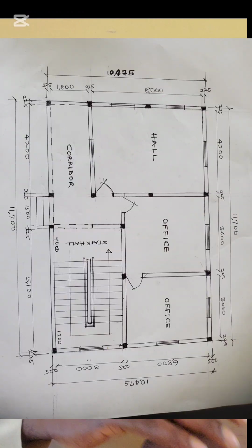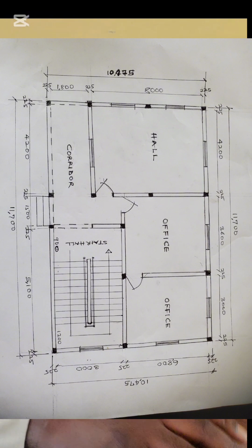So, in every design, you must look at the architectural design, then identify the points you have to put your columns. Then after that, you now arrange your floor, to state the type of panel you have, how many panels you have, then you number the beams. So it is with this you can start your design.